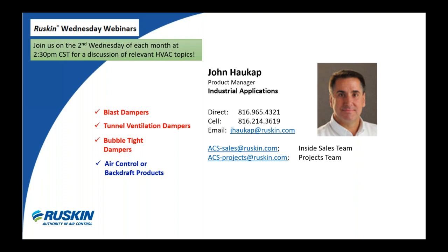So if you want that done, you need to let the person quoting the job know that, and they would include the price of that in your proposal. So yeah, that's a good question. And the testing we typically do here for folks is pressure drop testing, leakage testing, high temp testing, cycle testing. And if other testing is required, like seismic testing, sometimes we contract out to another third-party laboratory who can do that. We don't do seismic testing here. We do provide seismic calculations from our engineering team.